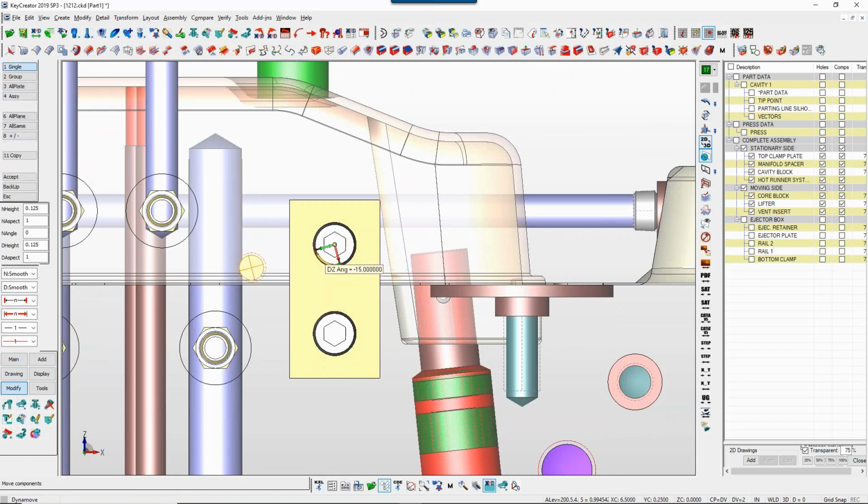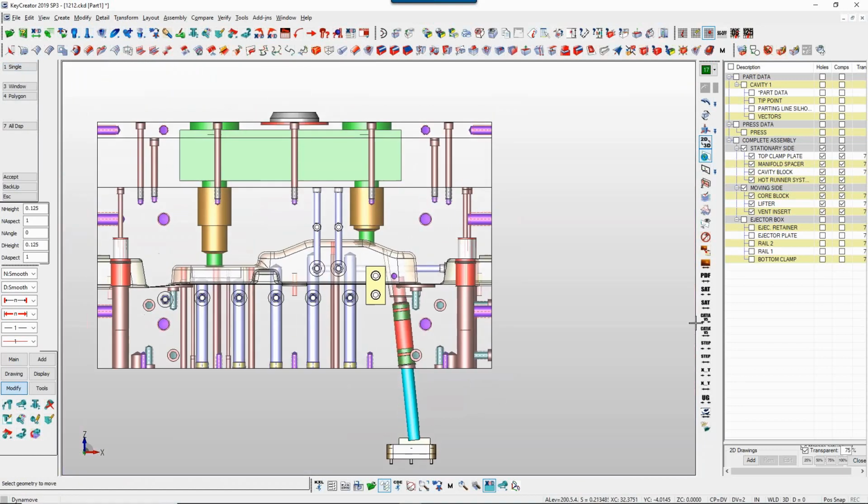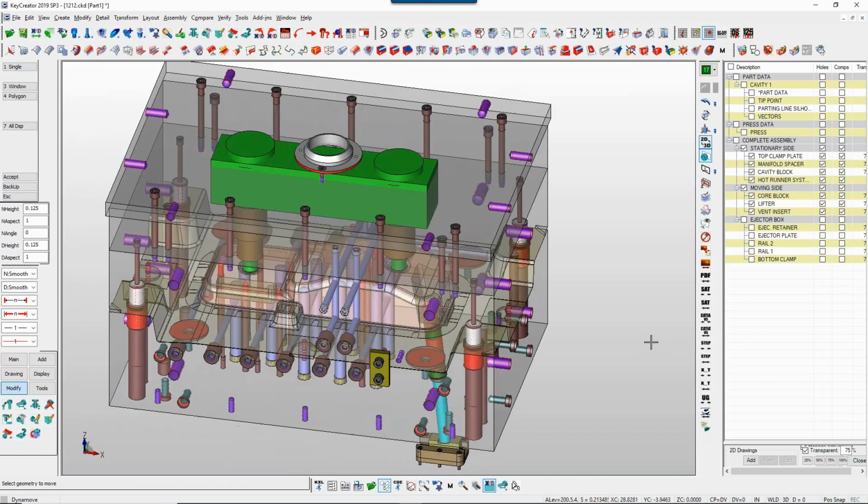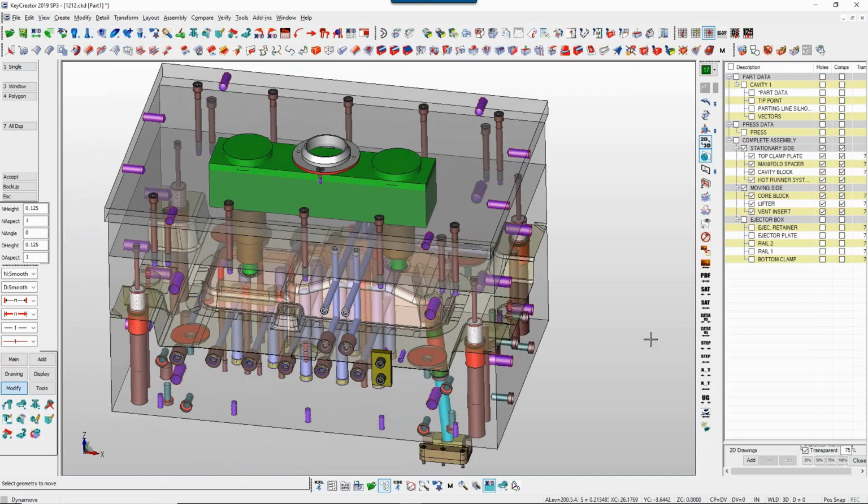And then from there I can take it and rotate it to wherever I want. So I can manipulate just parts of the assembly if I want, or I can manipulate the whole assembly. So maybe I want it just the other way. So it's really easy. You can obviously create custom assemblies for wear plates, your hydraulic cylinders with all the fittings on them, your water manifolds with all the fittings on them, things like that. So you can very easily and quickly place that stuff in.